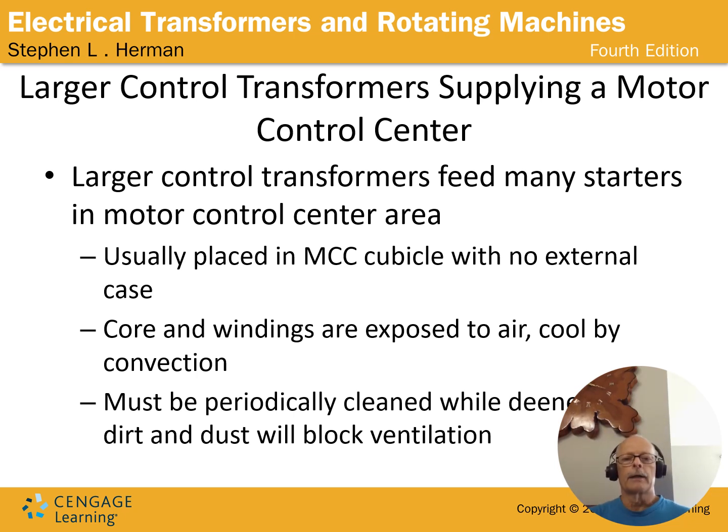Larger transformers are controlling power to a larger motor, and these are interesting transformers. They may feed multiple motor starters and do a number of jobs within a cabinet. Sometimes they're placed within the MCC cubicle, and they don't have an external case, so they're just there. Once again, just like I spoke of a minute ago, they're cooled by convection. Warm air rises, pulling cool air in, which soaks up heat and begins to rise itself.